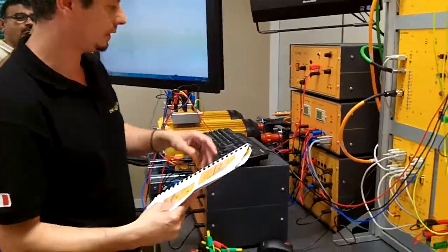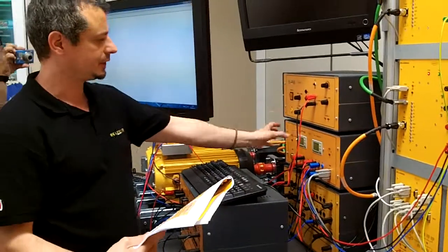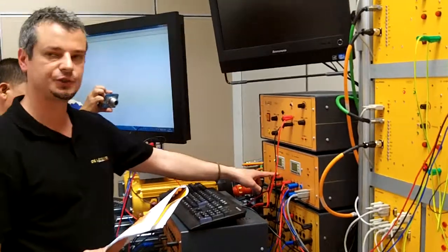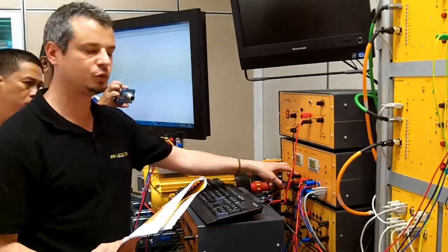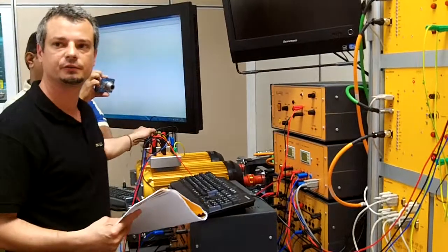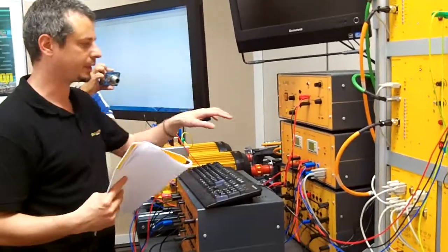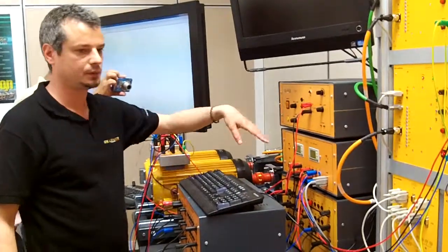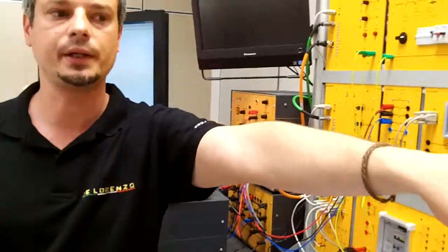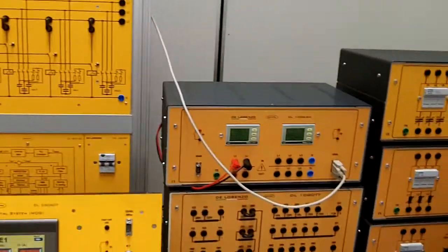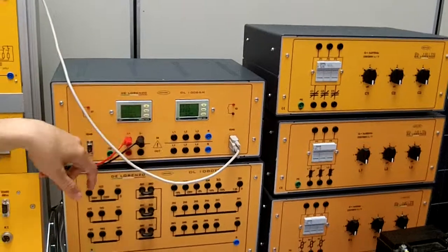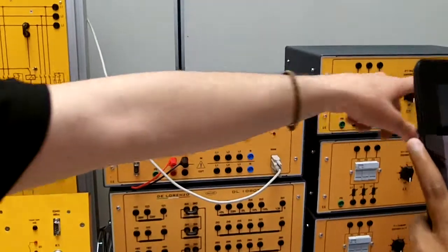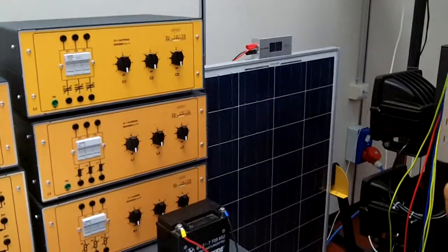So this is the module transformer, and this is another electrical measurement, 3-phase and DC. You need to control the DC because you have an excitation, voltage and current, so you can collect data coming from the DC generator. And the other one, I use channel 2 address 20, address 21, to collect data coming from the step down transformer and from the photovoltaic system, DC voltage.